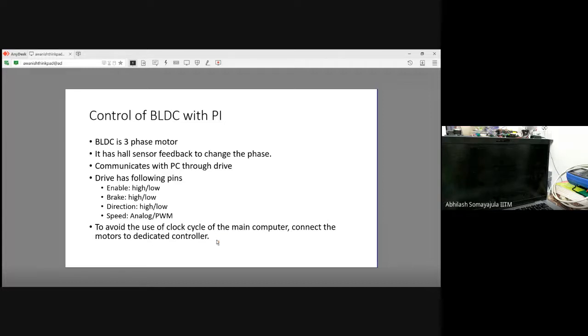So you have any analog voltage. Let's say, for example, you want to read your battery voltage, up to 12 volts. If you want to read your analog voltage from the battery, you can just plug it into the analog input of your Arduino pin, and then it is quantized and sampled, and converted into digital form. So it will give you some digital value corresponding to that. So this is how it works. But we are not using the analog input right now. We are only using pulse width modulation.